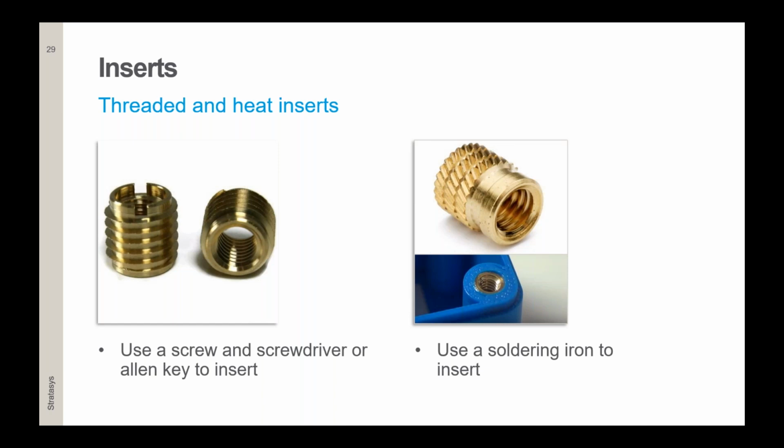You can use Insight software or GrabCAD Print software, and there is a menu after you slice a part. Put the Z pause inside, and the printer will pause on that layer, leaving the part open where you can insert. You open the door of the printer, insert, for example, a nut, close the door, and continue the print. And I will show you that in the last session.